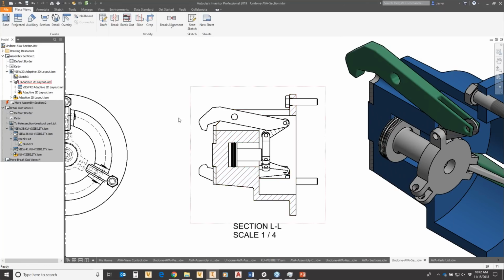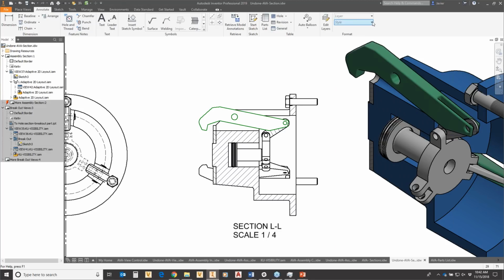As I'm moving along here, here's another option you have in terms of selecting parts. So when you do select these components, these all get assigned to layers automatically, visible edges versus hidden edges, you name it, right? So if you ever want to just change or highlight a part, you can right click and make sure you're set to highlight the entire part. We can select it, and on our annotate tab, it should show you what layer that geometry is on. And so it should make it easier to do that. But now that I've got the part, it's kind of hard to just change layers. It doesn't show up here.